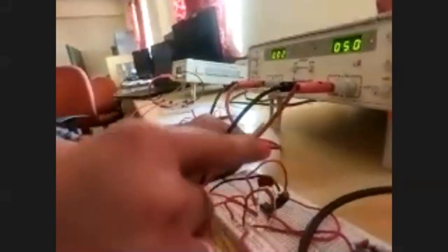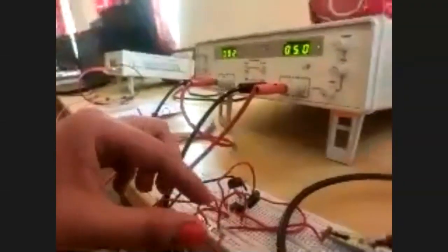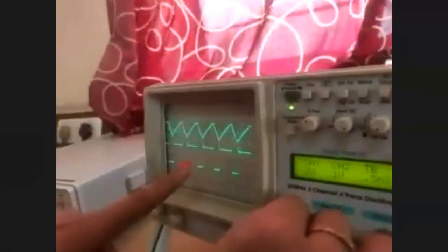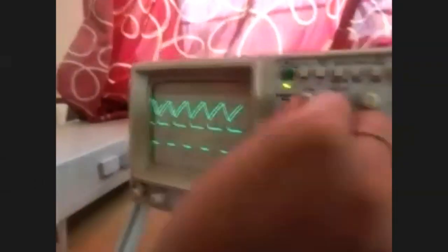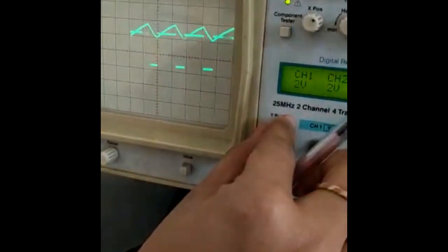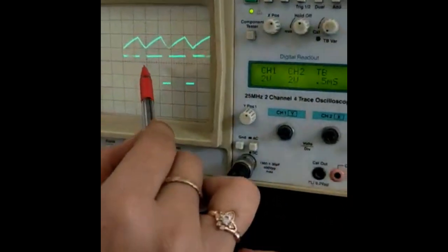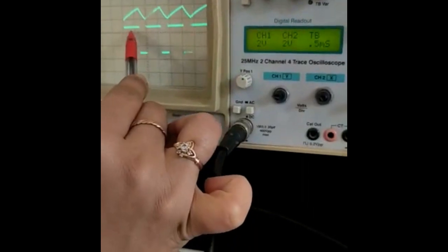So in the astable asymmetric multivibrator, T on is greater than T off, or T off is greater than T on. So from this we are going to show. When I connect the output across pin number 3, we are going to get this. So you observe here the on time waveform, and here T on is greater than T off.